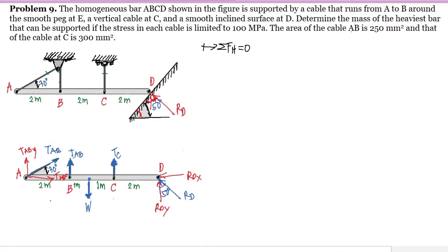Now for the horizontal forces, as you can see here, only the horizontal component of TAB and the horizontal component of RD are present. The horizontal component of TAB is directed to the right, so it's positive TABX.